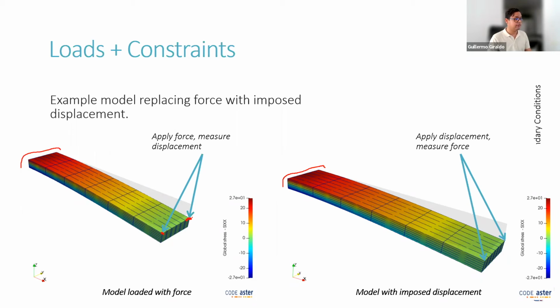So if you apply this principle, you think, okay, I'm applying a force because I've been told that the assembly that I am analyzing has to withstand a load of some value, right? That's what you need to model. You need to find the response against this load, but then you cannot get the response because you are getting a divergence. So what is happening? I'm applying a force and there is no reaction to balance that force, and I'm getting an infinite displacement.